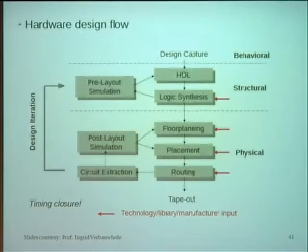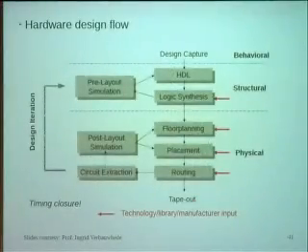Then you transfer it to a lower level language, normally called HDL, hardware description language, in many cases Verilog. And then you do synthesis, like when you write C code and compile it to generate assembly code.